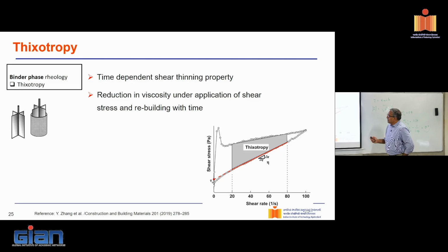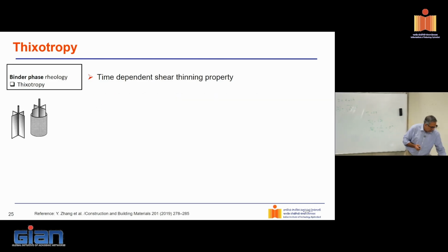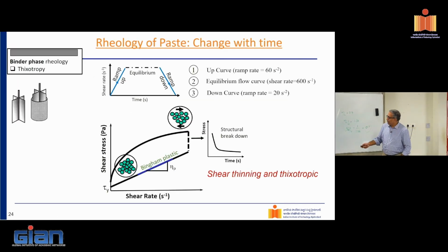So the converse of it, suppose I smash the structure, I shear it at a constant strain rate, I smash the structure, all these floccules break down into smaller flocks. Now the question is, can it still keep its shape? Possibly not. So what would I do? I would basically do this experiment where I would smash, so let me go back here. I would smash the structure here and then ramp it down to 0 strain rate.